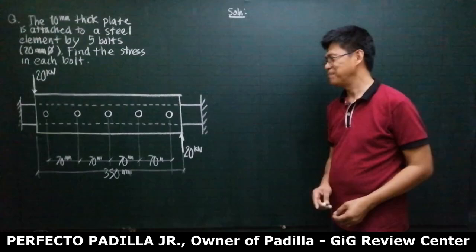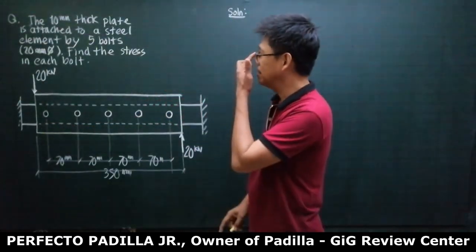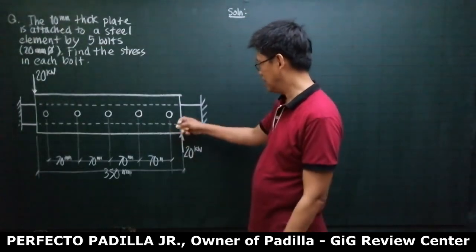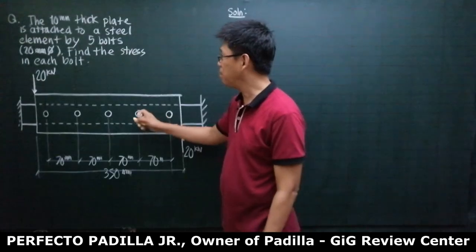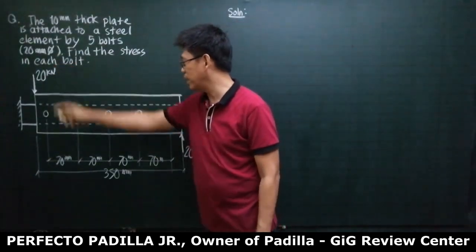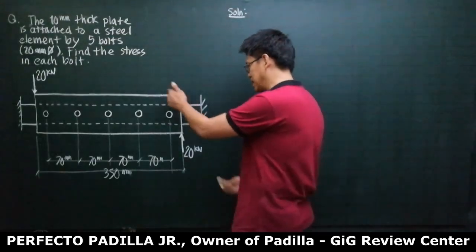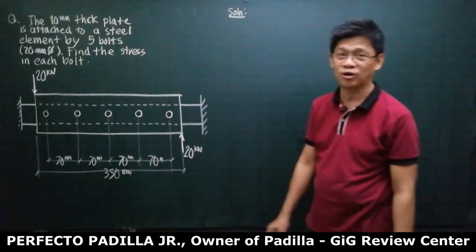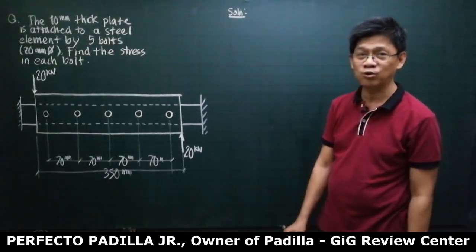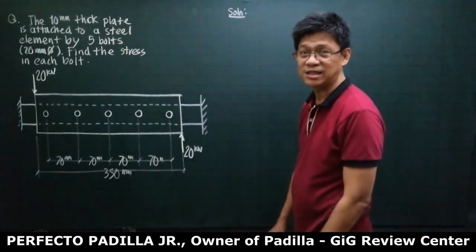Let us solve this one. We have here a plate that is 10 millimeter thick, and it is attached to another steel element, this one, by 5 pieces of 20 millimeter diameter bolts. So this plate is subjected to this torque of a pair of 20 kilonewton forces, 350 millimeter distance.